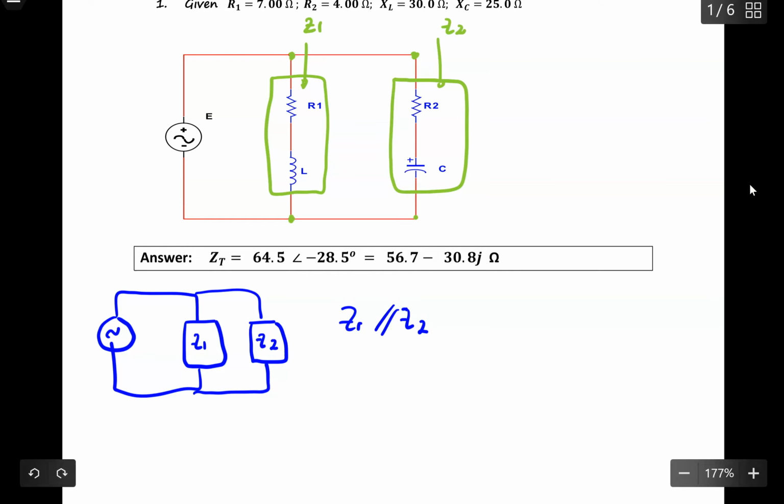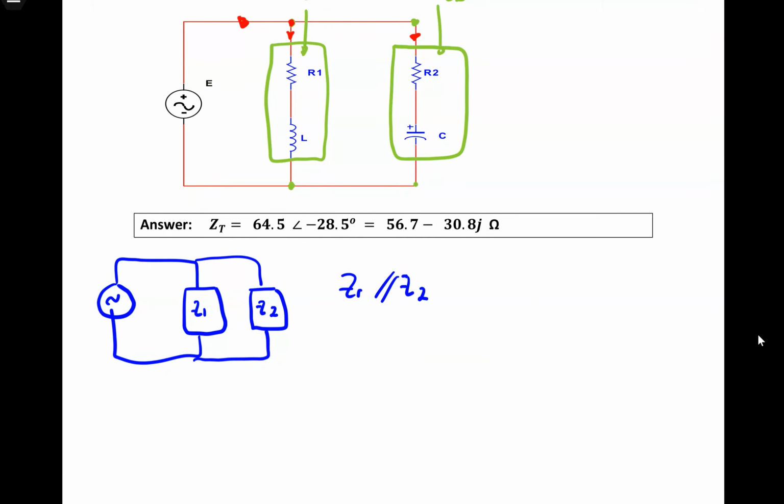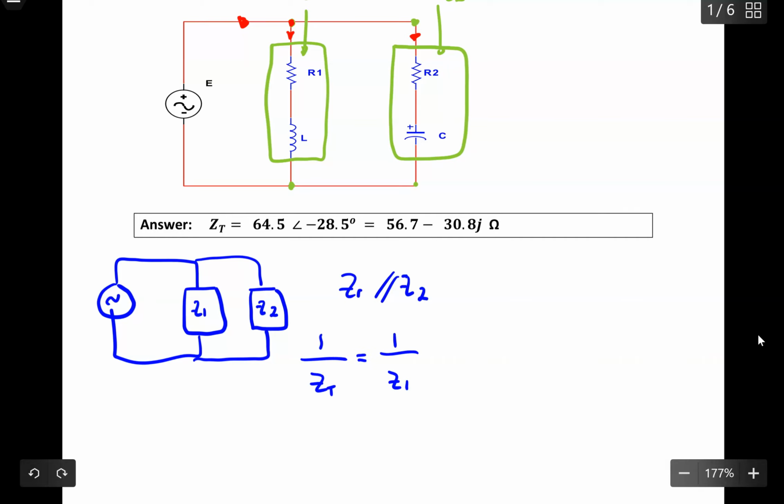If you generate the currents going through this circuit, right at this node it will split into two. As soon as you see the current split into two, the components here will be parallel to each other. In terms of impedance, measured in ohms, the formula is: 1 over Z total equals 1 over Z1 plus 1 over Z2.